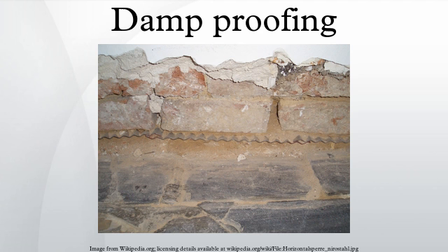Masonry construction. A DPC is a durable, impermeable material such as slate, felt paper, metal, plastic or special engineered bricks bedded into the mortar between two courses of bricks or blocks. It can often be seen as a thin line in the mortar near ground level. To create a continuous barrier, pieces of DPC or DPM may be sealed together. In addition, the DPC may be sealed to the DPM around the outside edges of the ground floor, completely sealing the inside of the building from the damp ground around it.